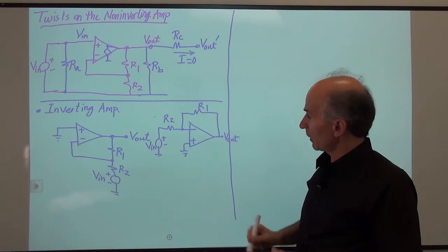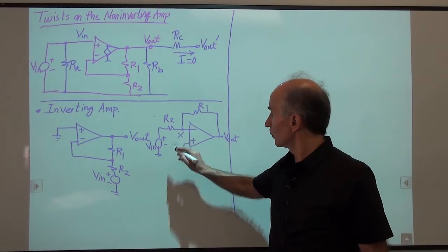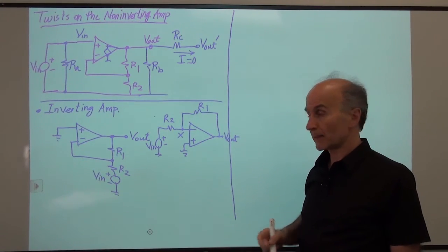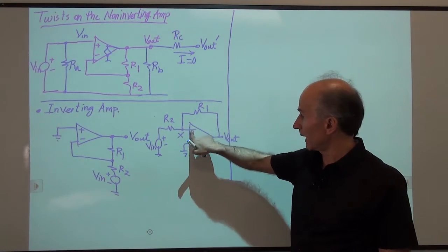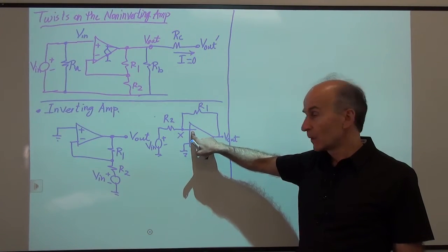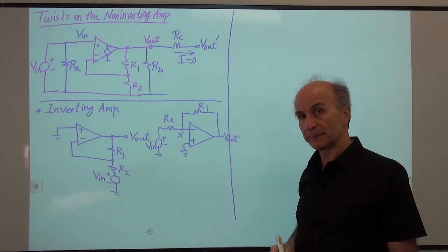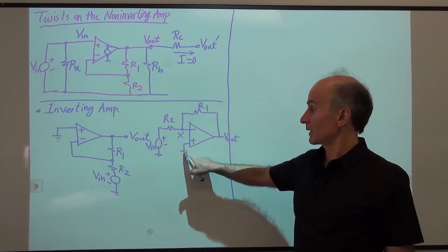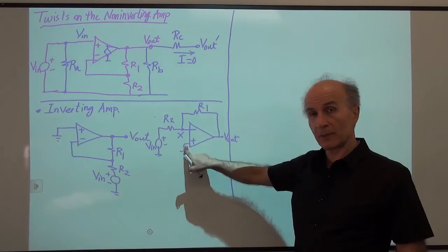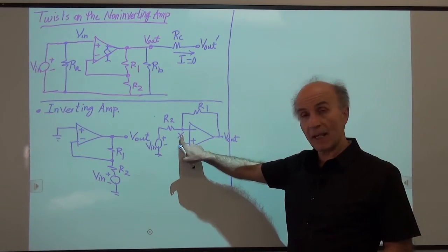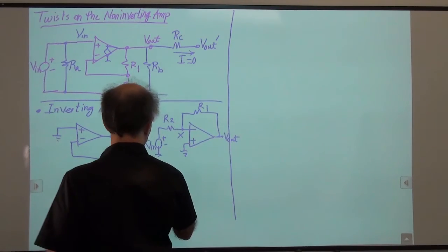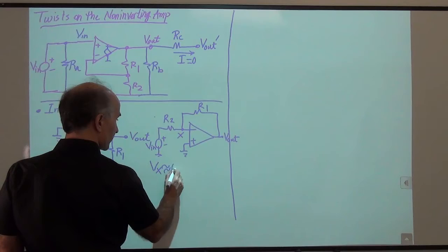All right, so we eyeball the circuit for a moment and then see what we can do here. There's a node here called X, right? This is where R2 and R1 and the inverting input of the op-amp meet. What can I say about the voltage at node X? Well, we see that this voltage is 0, and the op-amp wants to make sure that the other input has approximately the same voltage. So I can say that Vx is also approximately equal to 0.